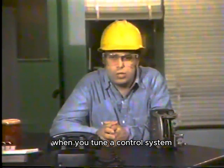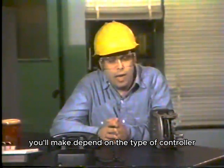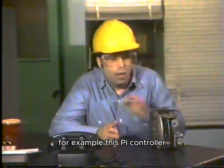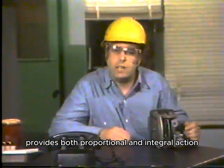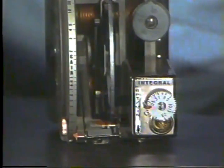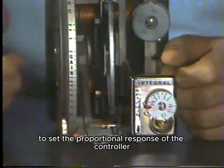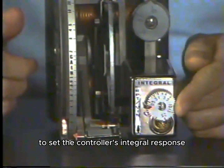When you tune a control system, the specific adjustments you'll make depend on the type of controller and the process being controlled. For example, this PI controller provides both proportional and integral action. When tuning it, you have to make at least two separate adjustments: a gain adjustment to set the proportional response of the controller, and a reset adjustment to set the controller's integral response.